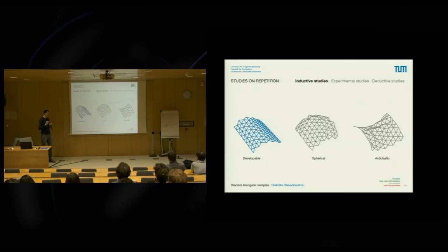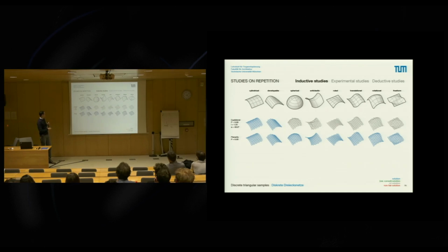And I just want to point out two insights I had. The one insight is that triangular meshes are very restricted. Really, all they can really do is, I'm just quickly going to go back, they can really only do cylinders or developable shapes. Any other shape is not possible if you want to have same length or same nodes, because they both exist coherently. So only if you want planarity, then you can do anything with triangles, because any triangle is always planar.